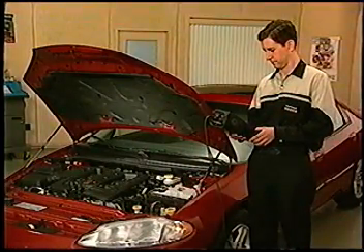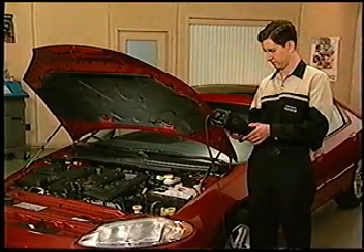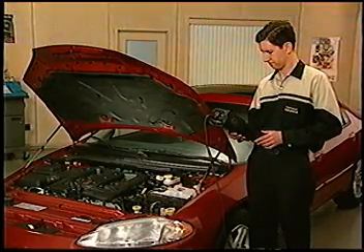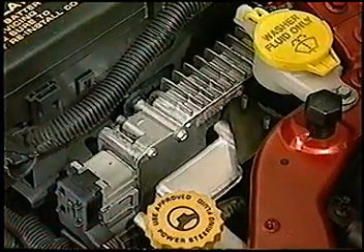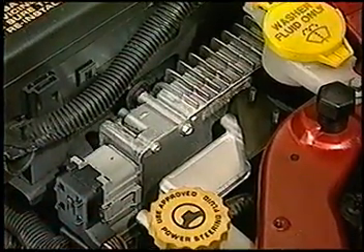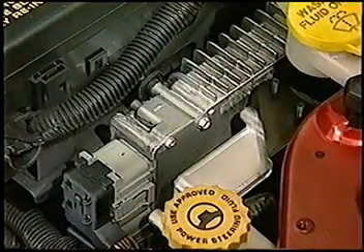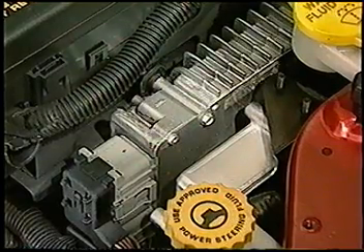Once you know how to access and interpret OBD2 data, it makes your job easier because it provides detailed information about engine and emission systems. In onboard diagnostics, the PCM runs a series of diagnostic monitors to test, detect, and identify emission-related faults in the vehicle.